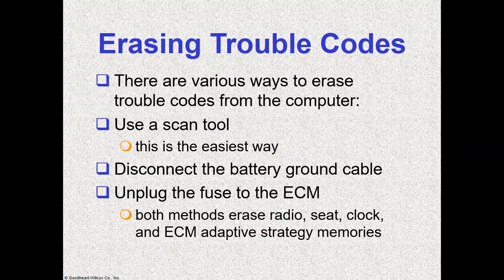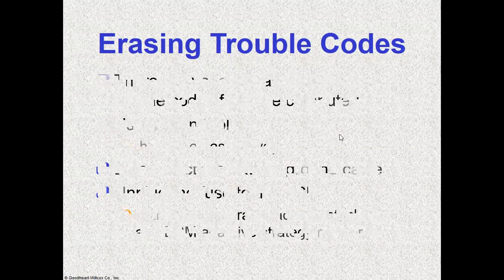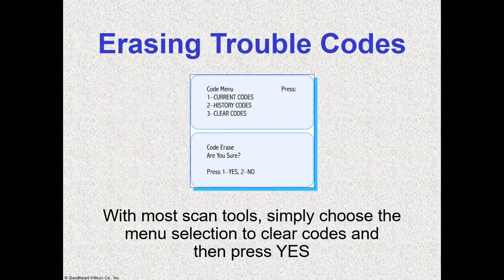Sometimes we clean the throttle body on vehicles like Toyotas, and when we're done the vehicle surges, idling up and down, up and down. So we can use a tool to erase those adaptive memories, or pull a fuse, whether it's the TPS fuse or the injector fuse, for a particular time, probably like 5 minutes or so, and wait for that code to lose memory.